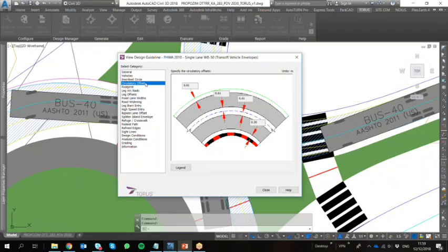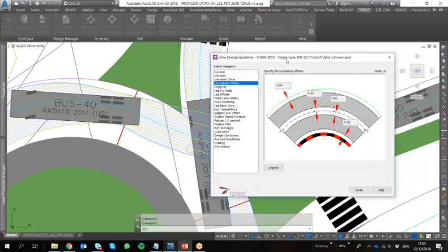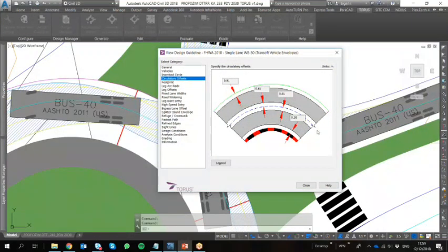The way I calculate the circulatory roadway width, so this lane width of the roundabout, is that I calculate the vehicle swept path, that's the gray area, and then I apply offsets from that. I apply 1 foot, 30 centimeters, to the inside between the swept path and the roundabout apron. I apply 2 feet between the swept path and one lane and the other lane.